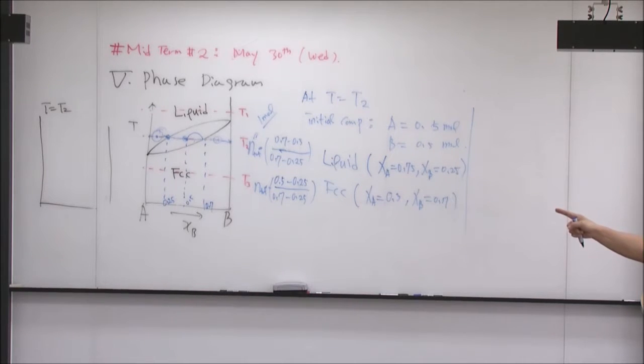Theoretically, the lever rule applies on a weight basis, not a mole basis. Sometimes mole basis is very confusing, and I'll explain one such case later. Theoretically, the lever rule has to apply only on the weight base, not the molar base.